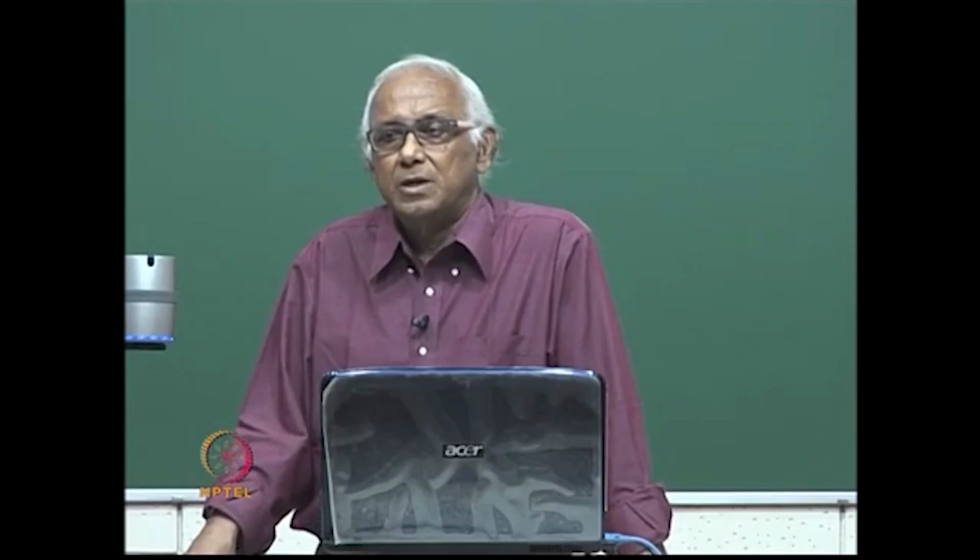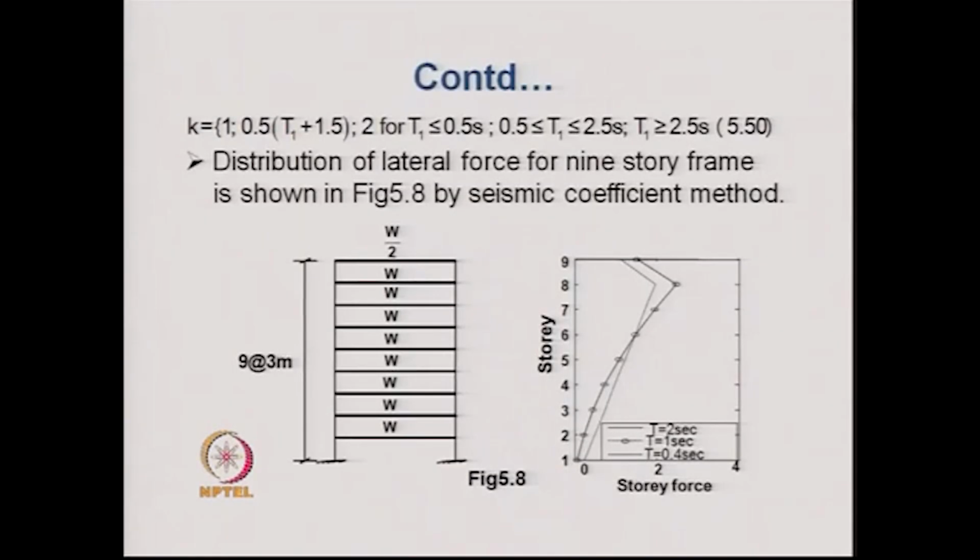Mind you that the base shear that was calculated was obtained by multiplying the total weight of the structure by the seismic coefficient Ch, obtained for the structure's period calculated by the Rayleigh's approximate method.